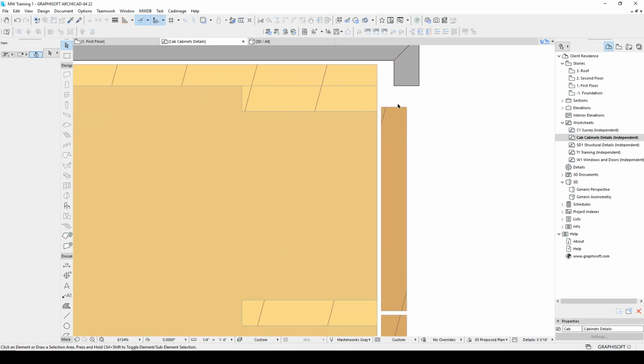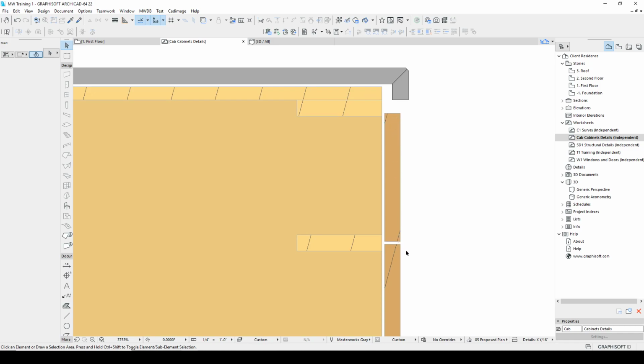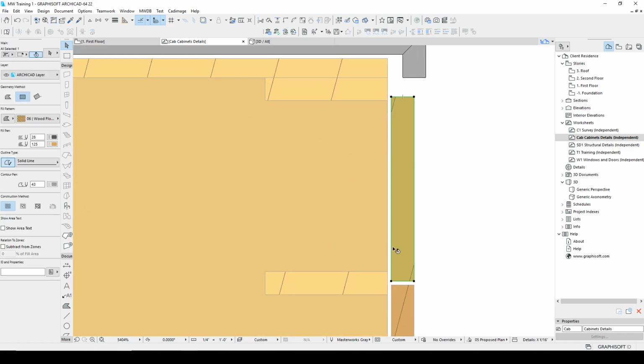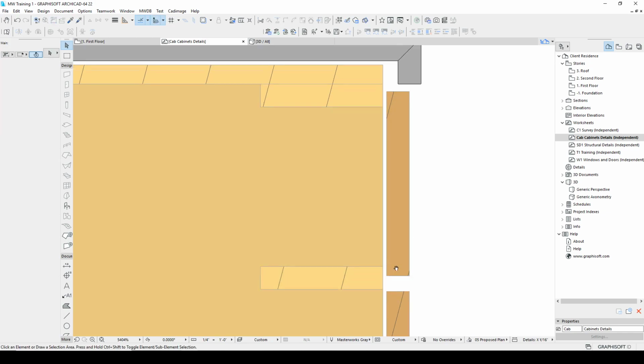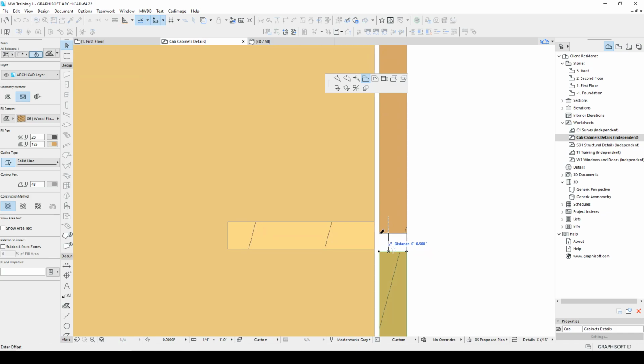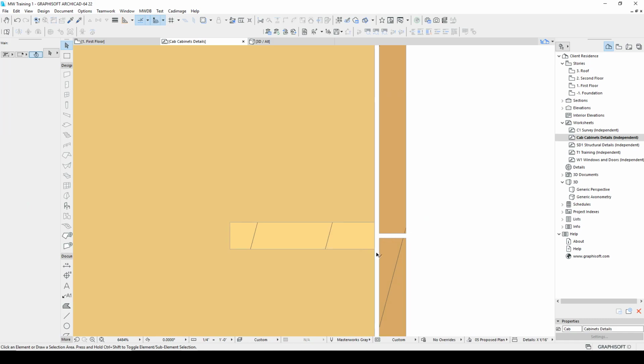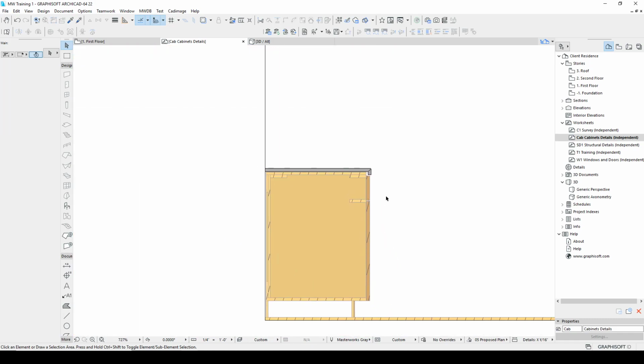Now we've got it. Now that these are the right size, we actually might want to move these up, and this is just going to be based on your standard. We often do a 1/4 inch below there. You'll notice this then needs to get extended. Move this to my origin to there and bring that down 1/8. And so now we have a standard cabinet. And this would be something you might want to keep in your file or in a standards file, and then just adjust it as the job requires.